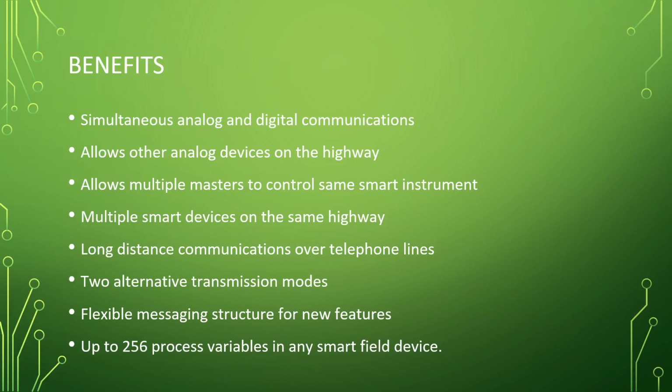So there's HART. It's great in the long run. It's reusing wires that are already there. Think about the time savings that would have you in industry. It's like, oh, we need more information from that one sensor. Okay, let's put a HART sensor there, put a HART input on the analog card, and we don't have to run any new wires. So yeah, it's going to cost you new devices, but it doesn't cost you any man hours to run the wires, which means that your upgrade time could be a matter of minutes, right?